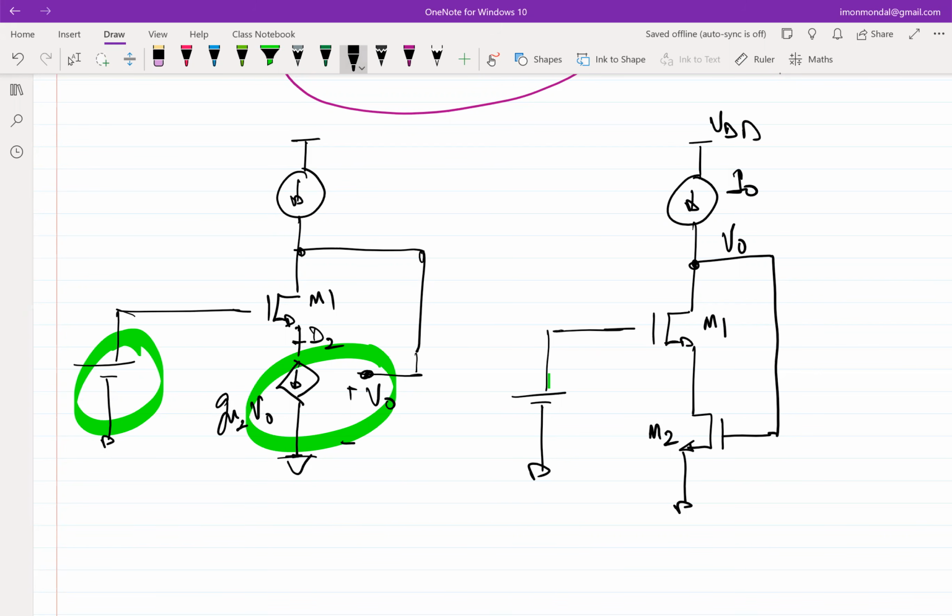So I have to first establish, if I connect up my circuit like this, connect up a couple of transistors like this, whether this is still in saturation or not. If I have to figure out whether this is in saturation, what is the most important thing that I have to look for? Pardon? VDS and VGS, right? So now you have two transistors. You can choose which one you want to attack. So let's choose M1.